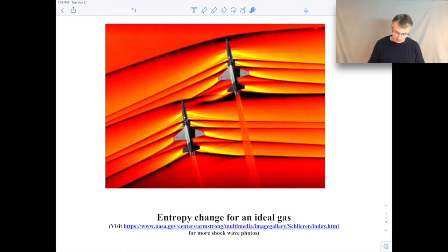And you'll see, like here, for example, you get this rapid change in air density, and that's what's called a shock wave. So shock waves show up when you deal with supersonic flows that are faster than the speed of sound in that substance. It's a topic that's covered in compressible gas dynamics. Across a shock wave, you get very rapid, essentially step changes in properties. So you'll see a sudden increase in the pressure of the air going across that shock wave. That gives rise to a sonic boom that people hear.